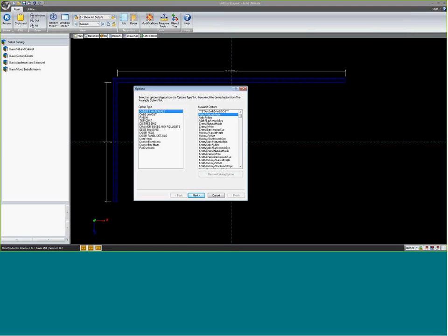I'm just going to go ahead and pick alder with natural maple and base layout. 99% of the time you're going to want to select Euro for your room. Even if you're doing a face frame job, you'll want to select Euro for your room. We're going to use overrides on individual cabinets for the face frames. That sounds a little silly to do it that way, but we'll show at a later time why that's important. But you'll almost always want to pick Euro from this menu.